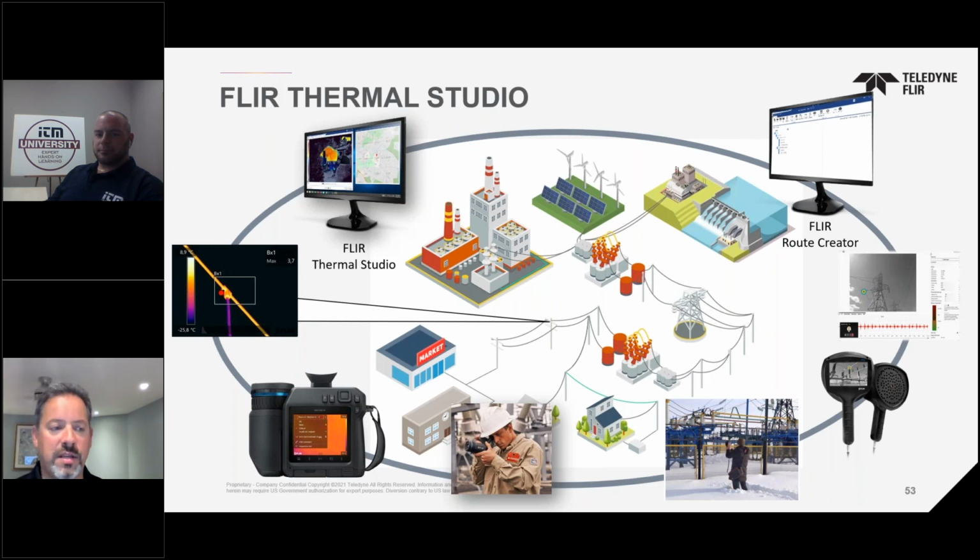But to measure emissivity automatically, you basically have to compare two wavelengths. There are devices called spectrometers that look at different wavelengths coming off the surface, compare them, and do an automatic calculation. There is a way to do it, but we don't have the cameras ready to go, at least not in the Teledyne FLIR line. Again, Teledyne has a lot of other divisions that might have something like this, but in our particular case, we don't have an automatic emissivity measurement system.